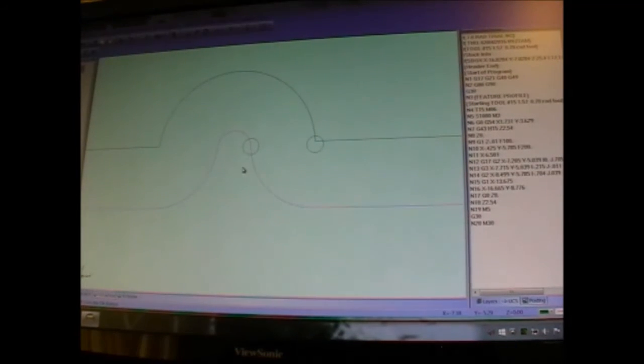Your milling software, your CAM software, in conjunction with the post-processor, will produce code, and it'll be either in radius arc format or center arc format, and either in incremental IJ mode or absolute IJ mode.